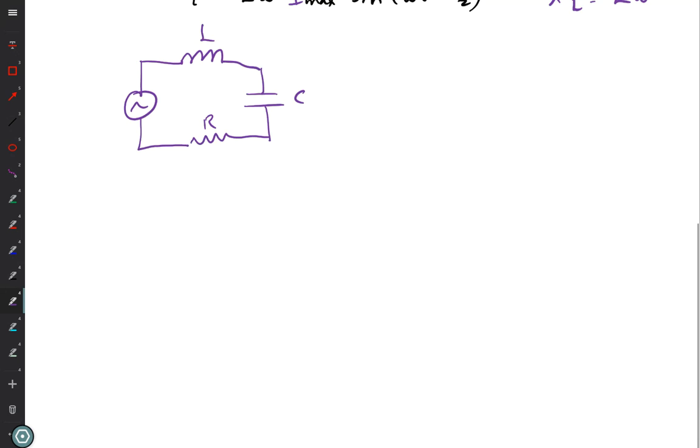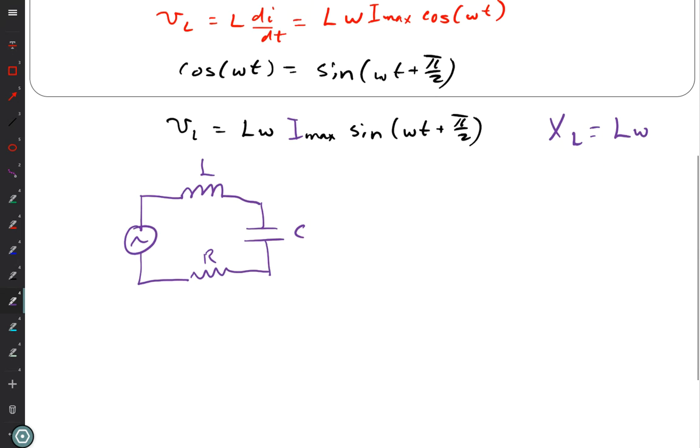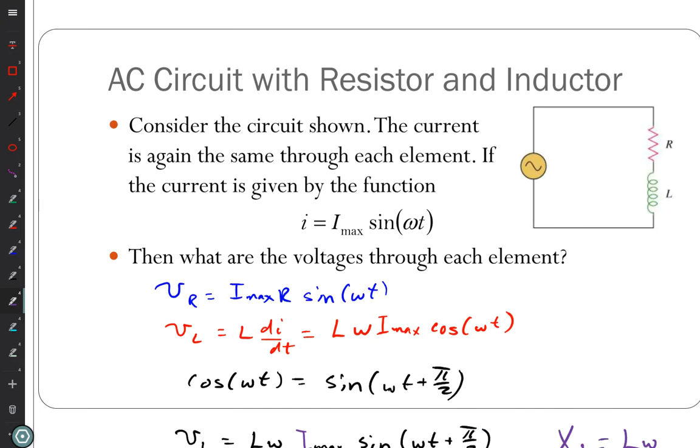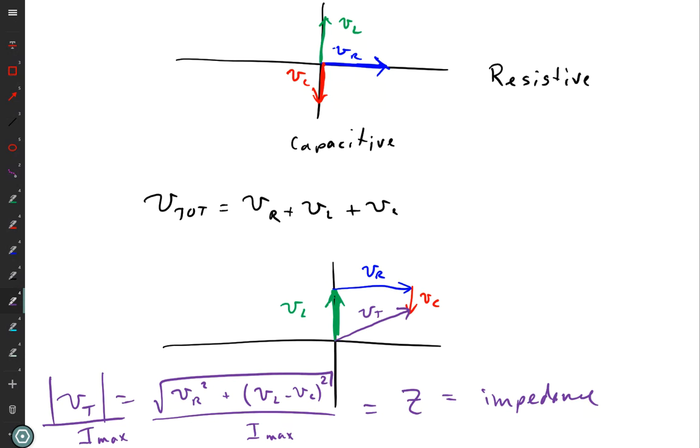If we look back at our picture here, wasn't it here where, or did I not draw the picture? I was sure I did. Okay, here we go. Here's the picture. The phase angle here has for its opposite side VL minus VC, right? This distance here is VL minus VC. For the adjacent side, it had VR, but we can also use cosine using the hypotenuse.